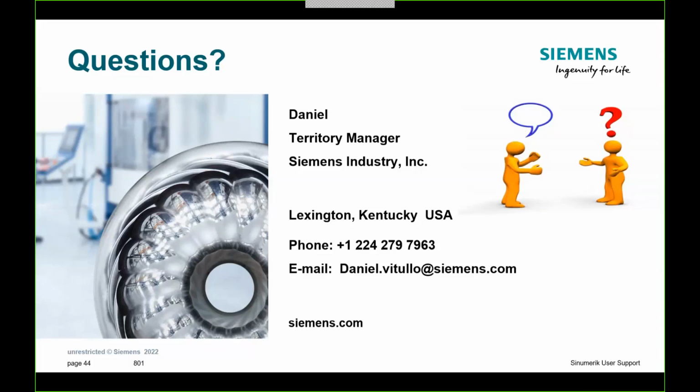What kind of parts would work best on a MILL-TURN machine? For me personally, my background is machine alignment prior to getting into the applications and service side of the world. One thing I can say for certain: the less that human beings touch parts, the more accurate they are. What I mean by that is the less I have to take that part from machine to machine to machine, the more accurate that part is going to be.